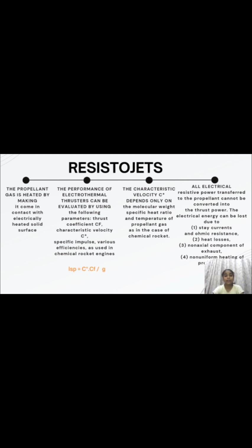Temperature of the propellant gas: the hotter the gas, the faster it can be expelled, leading to a higher characteristic velocity. In simpler words, the speed at which the rocket can shoot out its propellant, the characteristic velocity, depends on how heavy the molecules are, how well the gas can be heated, and how hot the gas is. These factors are crucial for the rocket's performance, whether it's an electrothermal or a traditional chemical rocket.